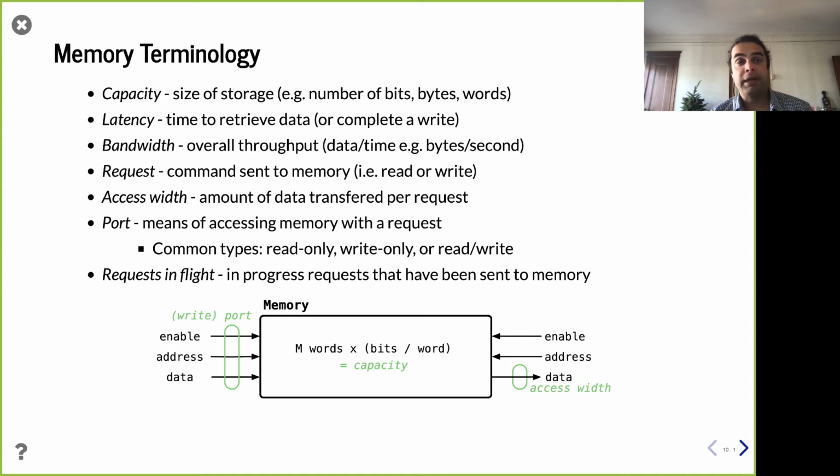So, for example, if I have a memory that has only a single port, that means I can only initiate a single memory request per cycle at most, right? Perhaps there are even limitations on that too. But if I want to do 2 memory transactions per cycle, I'm going to need 2 ports on that memory, right? And so the number of ports is going to be a really important design constraint, because depending on implementation technology, you may have a very limited number of ports, right?